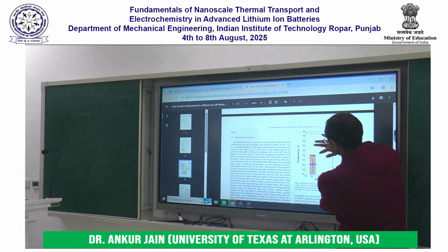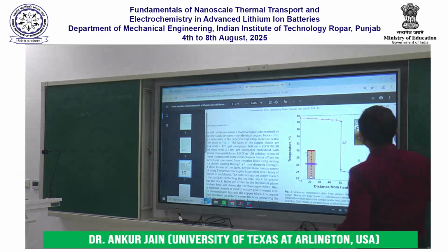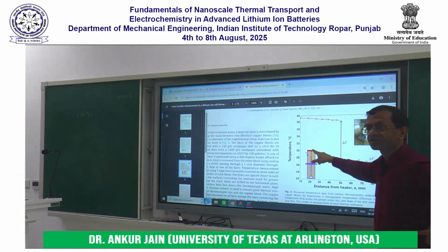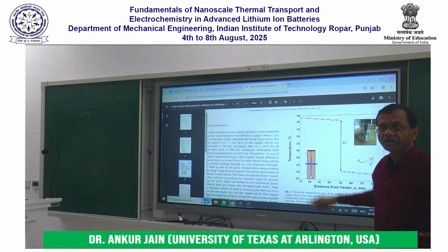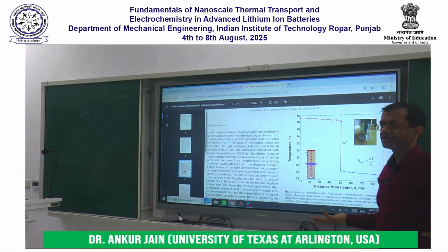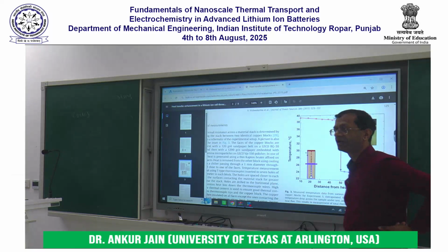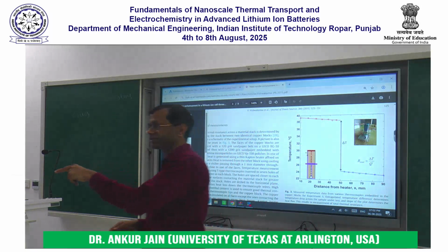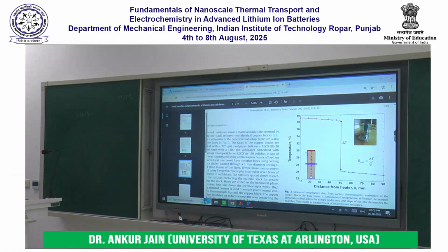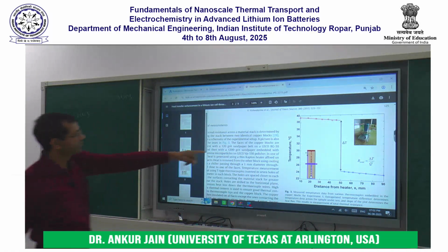in which we took 2 copper blocks. Why copper? Because copper has well-known thermal conductivity, and we drilled a number of holes in the copper blocks and inserted thermocouples on both of them, the hot side and the cold side.